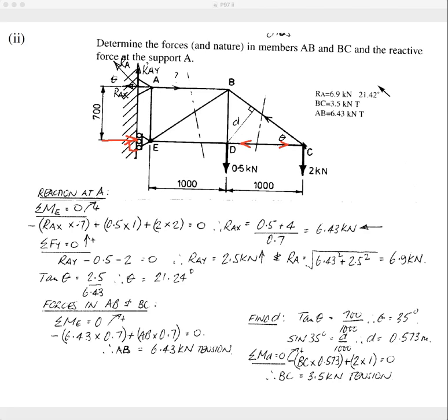You put your fist at that point there, with a pencil in your hand, and do what that force is telling you. If you push the pencil into your hand, you can see that it's in compression. Same thing here. Put your hand there with a pencil in it and push towards the joint, and that shows that that member is in compression. So don't get foiled by the fact that this looks like tension that's pulling it apart. They're internal reactive forces, so just use that method of determining whether they're in tension or compression.